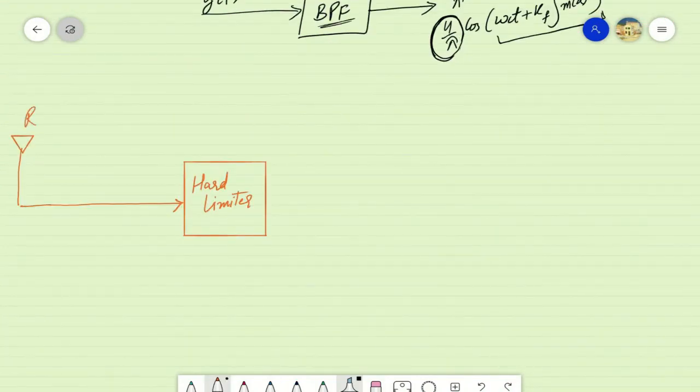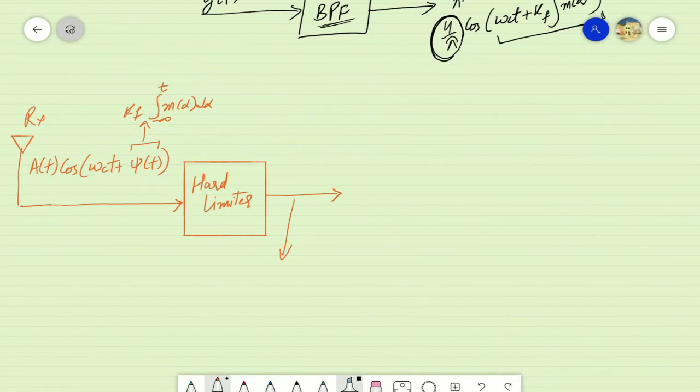So at the receiver, a signal with time varying peak amplitudes was received, instead of its peak amplitudes being a constant number ideally. After passing this signal through a hard limiter, the hard limiter converted this input sinusoid into a square wave by retaining the information of frequencies, while forcing its amplitudes to +1 or -1, as we received.